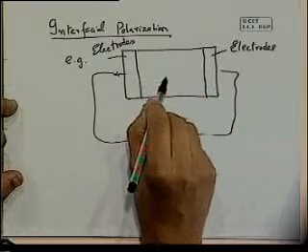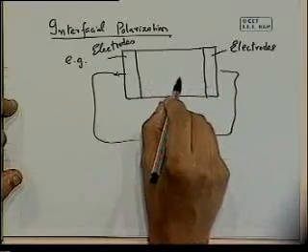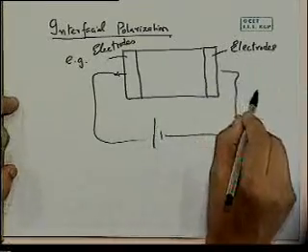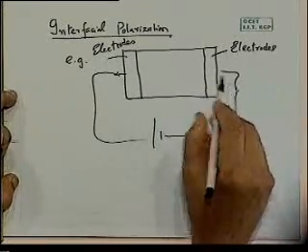What happens when the ions come to this interface between the dielectric and the electrode? The ion simply can't go on into the metal, right? It will come to that interface and get stuck. It has nowhere to go. Even if it's being pushed by the field that is applied, it has nowhere to go.